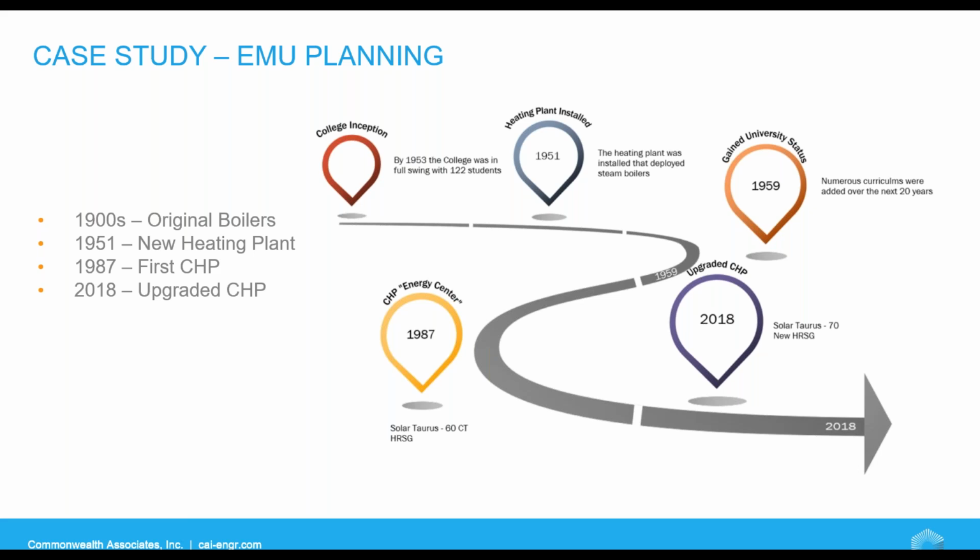Natural gas was burned in an industrial grade gas turbine coupled to a generator, producing roughly half the electricity consumed on campus. And as Mike said, it was only operating at an efficiency of about 30%. But with the addition of the exhaust heat from the CTG used to convert water to steam, it improved the efficiency and also provided for campus heating and cooling.